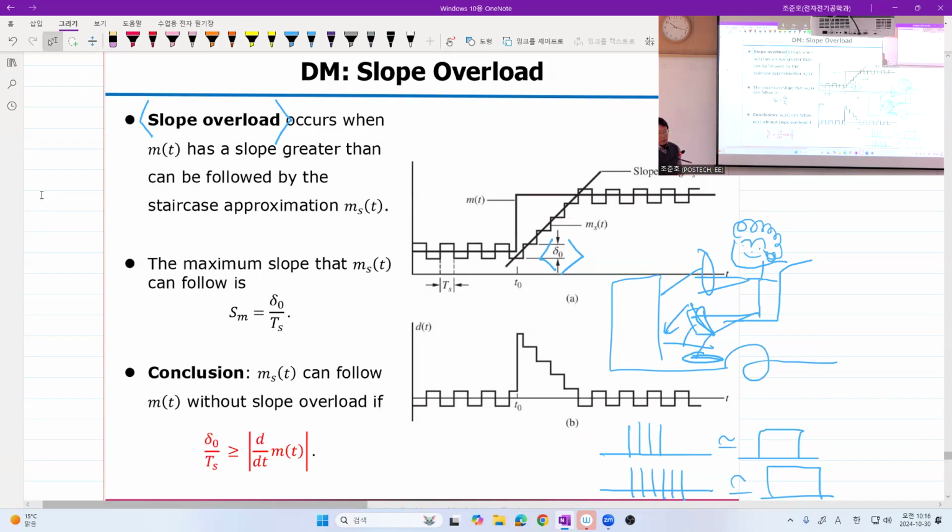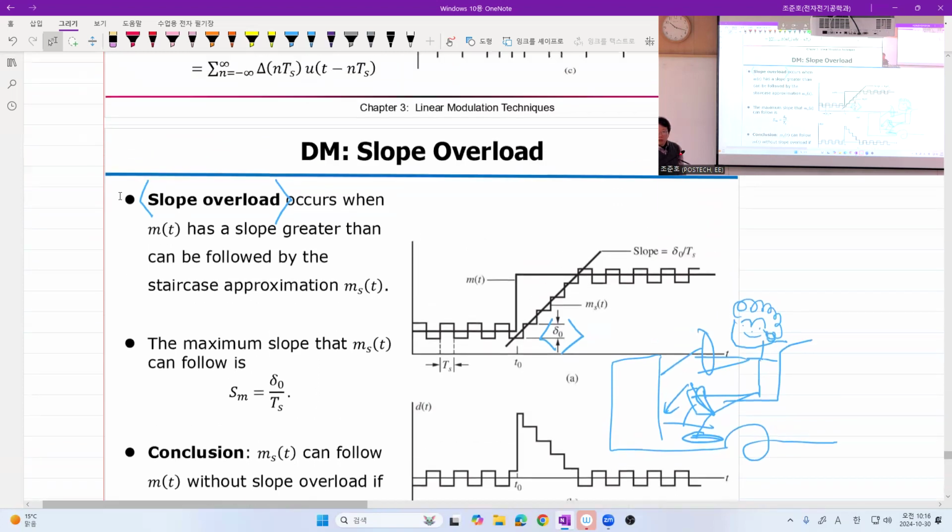By the way, in delta modulation, if we assign very few bits, then we have a problem, because sometimes the difference may exceed our bit resolution. In that case, we can only keep up slowly. For example, we may not represent this big jump with a small number of bits. Then our delta modulated signal will be reconstructed following this line, and we have this error.